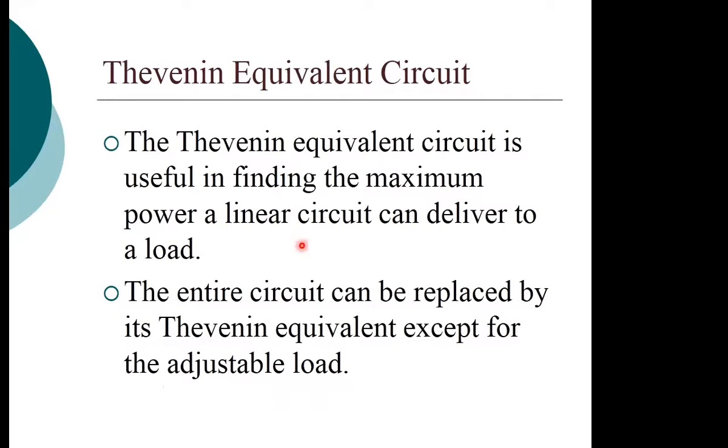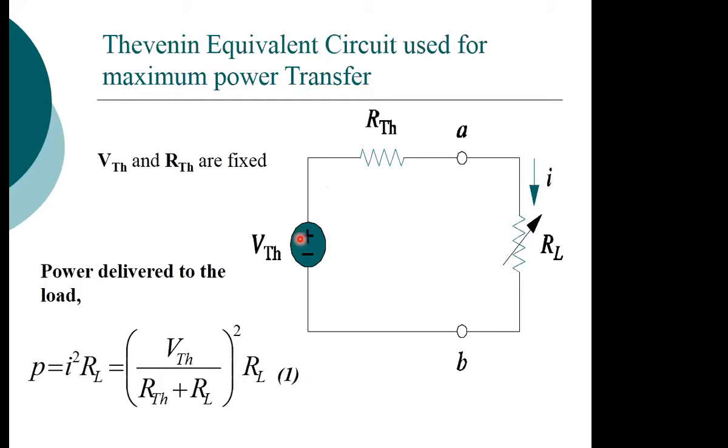And this can also be used in finding the maximum power in a linear bilateral circuit. That's why we had to do Thevenin's theorem first. But you realize that you can also find it in other forms. So that is our Thevenin's equivalent source, V Thevenin and R Thevenin. Then we have our terminals, and then the load is connected across the terminals to give us the terminal behavior.